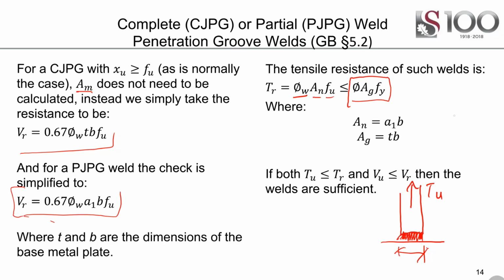We can also have cases where we've got to check a portion of a weld. For instance, if we wanted to check that of a fillet weld, that would be the tension resistance. But since shear is weaker, we normally ignore it. There may be exceptions when we require to test it, but this is the tension resistance of a weld, where that's in pure tension.